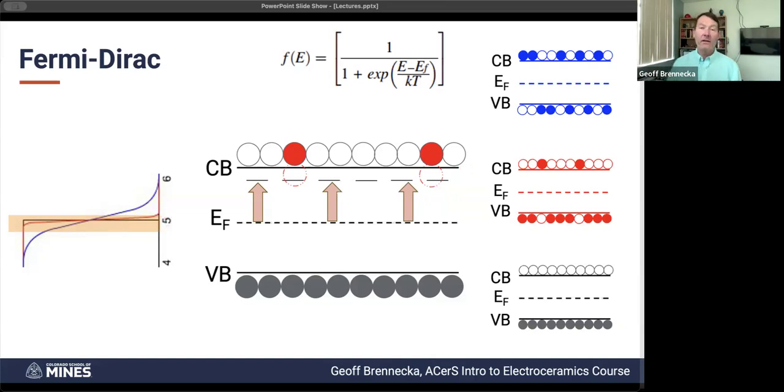control the conductivity of these semiconductors, not just by temperature, but by putting in a bunch of electrons that are easily available at room temperature. And then if we do it right, then we have a large barrier for any of these electrons to hop up, because we want to be able to control things by the dopant, not just by temperature.